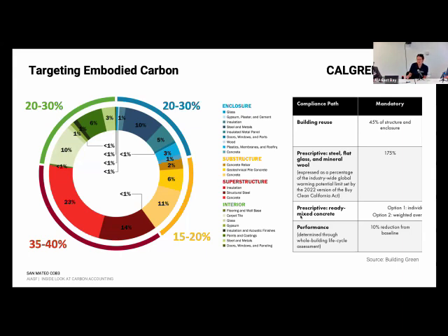And one way that I found we are kind of underutilized is really testing the question of whether this costs more. So for example, I can tell you that in the Bay Area, you can hit 20% below NRMCA baseline at no additional cost for almost all projects, because we took that same question and went to our 7 top concrete bidders in the Bay Area and asked them. They said, yeah, no problem. There's no additional cost, 30%, maybe a little bit more. Here's what you should plug in your estimate if you want to do that. And you can take that information and go to the client, and that client can say, yeah, I'm willing to cut down on our carbon footprint by another 300 tons at a cost of X.